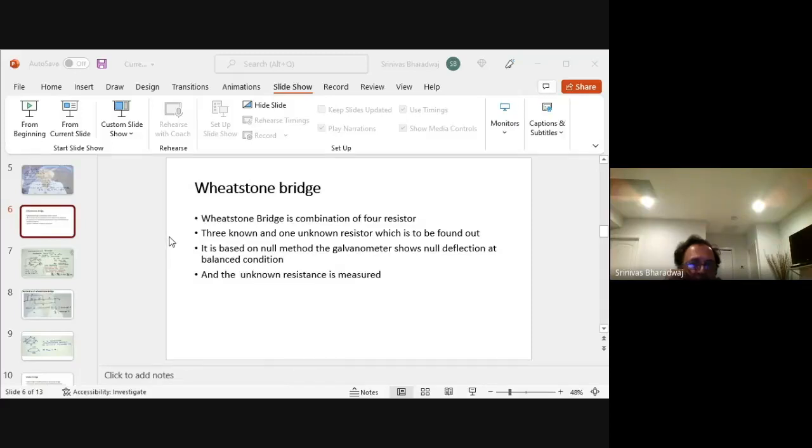In the second case, you close the switch and you still manage to keep the current zero. It means the cell sends a current, but there is still a null deflection, and that null deflection gives you a chance to evaluate R. Okay, so E equals phi L1, and therefore the corresponding R. So those are the two cases.